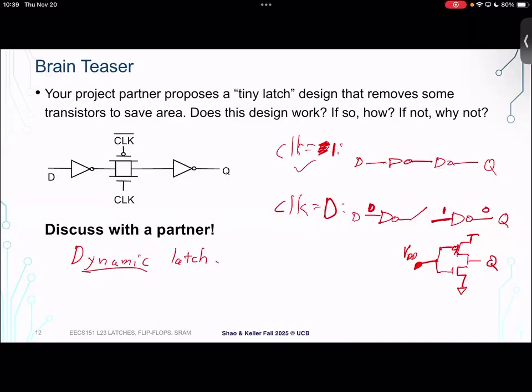So there are many different styles of dynamic logic design that people used. This is an example of one, this style of latch. But in a modern process, this stuff really went out the window in the 2000s or so. Leakage started to become much more severe. And today you wouldn't see a design like this used because it would be in danger of forgetting its value.